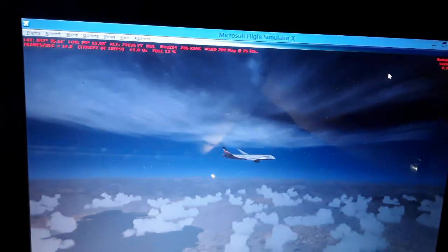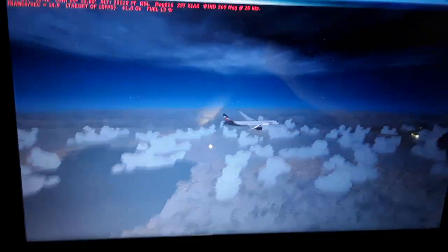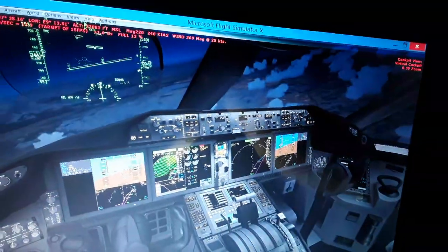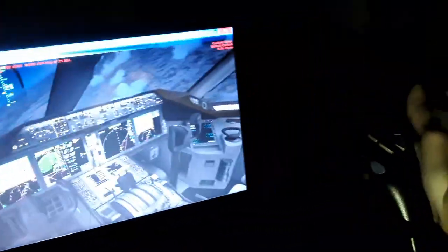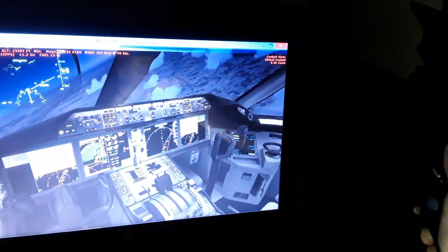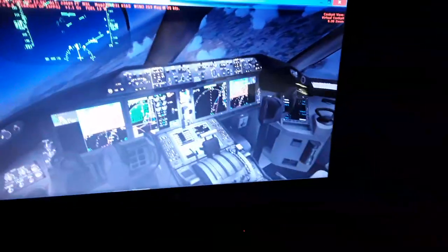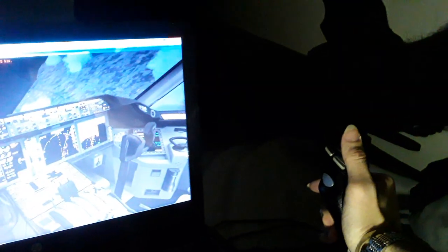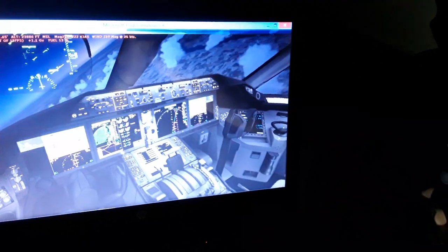So we're gonna make the turn, overflying the beautiful lakes here of Switzerland. We'll be aligned with the flight plan. You can see we leave the hands off, no problem. Still have no autopilot connected. We're gonna use a little bit more right rudder to make the turn faster and adjust the flight path of the airplane.